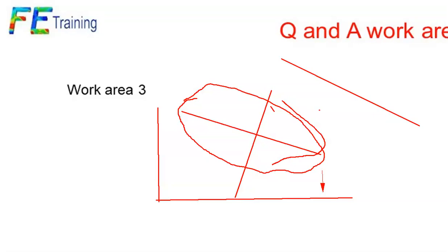Oliver says, what typical safety factors are applied to fatigue life in order to find a safe working life, assuming a design in which once a crack occurs, life to failure is very short? It's actually a bigger question than that. We could apply a safety factor, but we've also got inspection coming in. We also have a fail-safe approach, which means that if your critical part fails, there's another parallel path. We also have a damage tolerance approach, which brings in fracture mechanics to say, let's inspect this thing to make sure that it's okay.